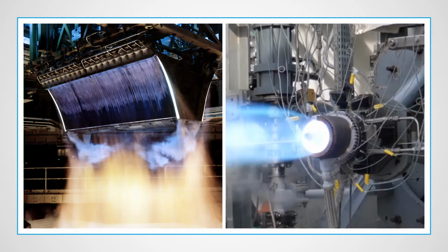When it came to this project, I had to choose between optimizing a toroidal and a linear aerospike. In the end, I ended up choosing a toroidal aerospike because the linear aerospike gave more points of failure, had more weight, and was harder to steer, which as a result gave an overall worse performance.